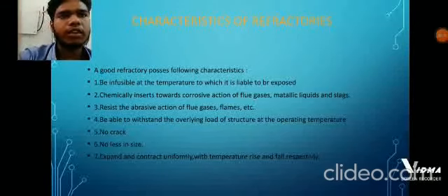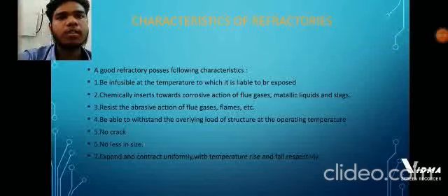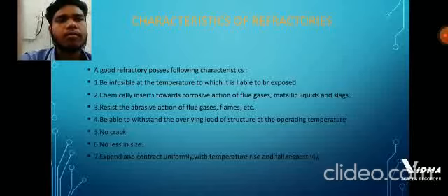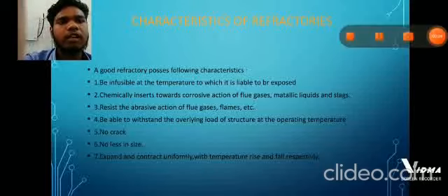Characteristics of refractories: a good refractory possesses the following characteristics. 1. Be infusible at the temperature to which it is eligible to bear exposure. 2. Chemically inert toward corrosive action of flue gases, metallic liquids, and slags. 3.